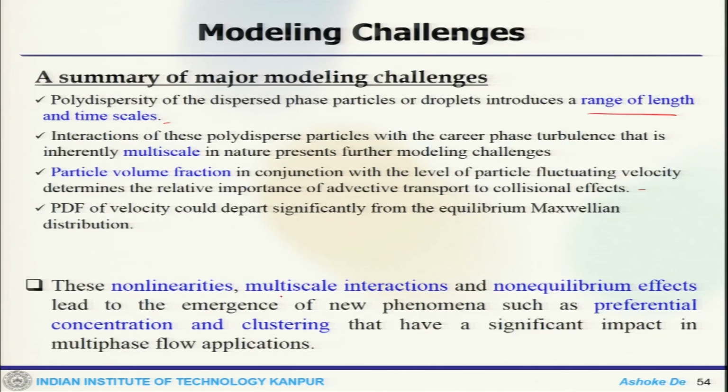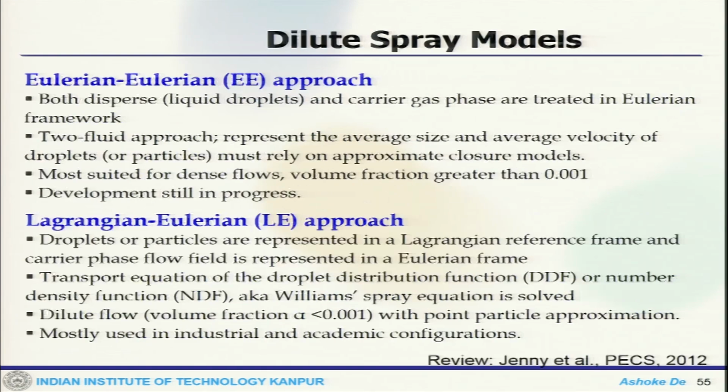Now, these nonlinearities, multiscale interaction and non-equilibrium effects actually lead to new phenomena such as preferential concentration and clustering that have significant impact in multiphase flow applications. So, essentially these are quite challenging. It is not uncommon to encounter a wide variation in the dispersed phase volume fraction in the same multiphase flow. For example, in a fluidized bed, the particle volume fraction can range from near close packed at the base of the bed to less than 5% in the riser. So, these are the things one has to consider.